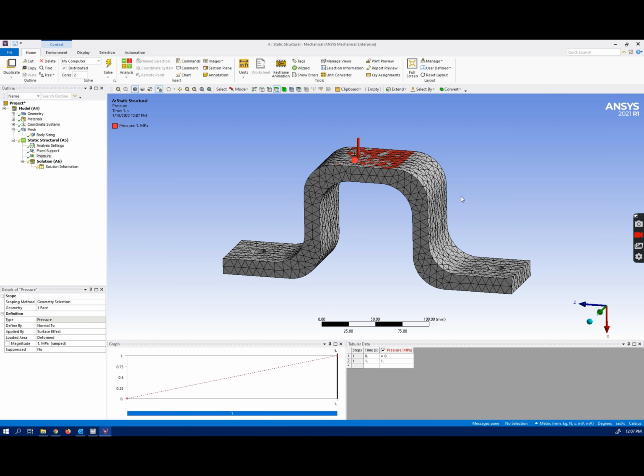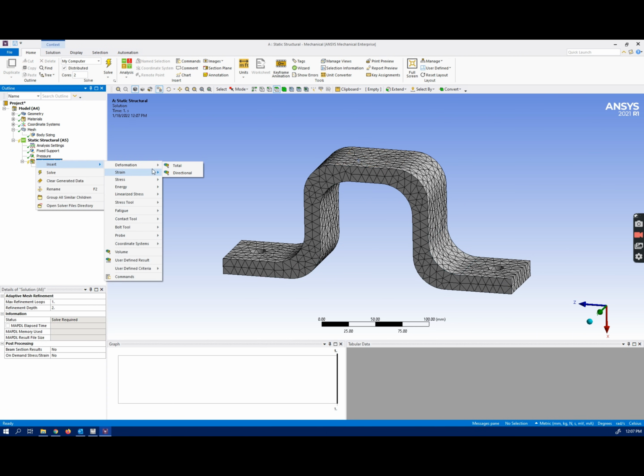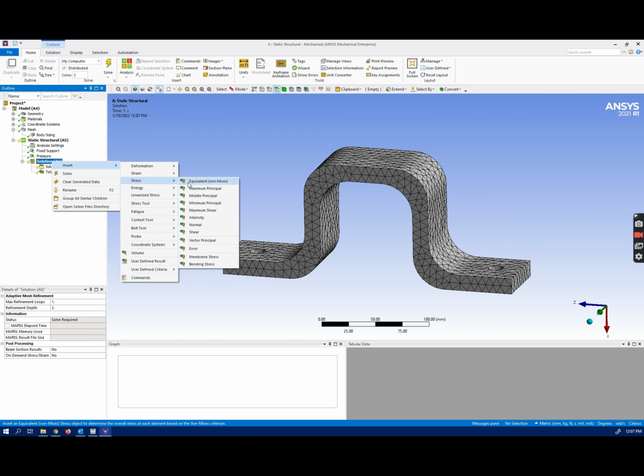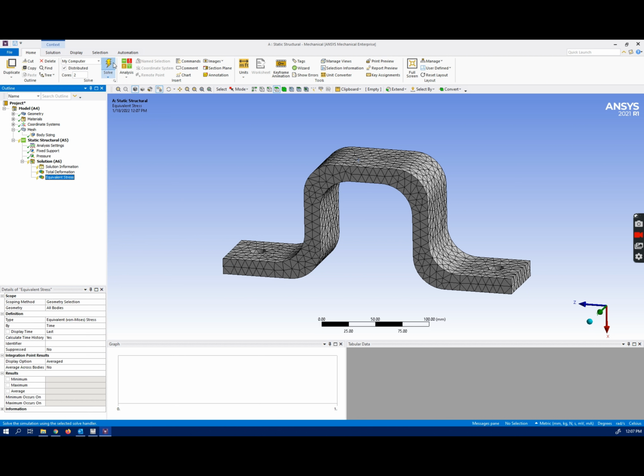With this arrangement, with these boundary conditions, I expect to have deformation in the x-axis, the main one which I'm interested in, and any vibration in x direction is going to be the one I'm interested in. We may have some natural frequencies in other directions, twisting ones, the other forms or modes, they are present, but I'm not going to focus on those. So let's check, for example, total deformation and stress and solve it.